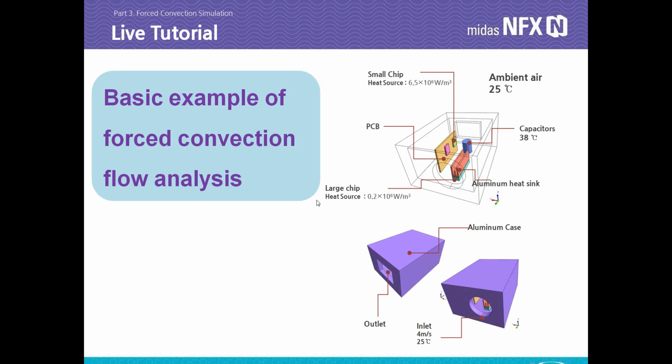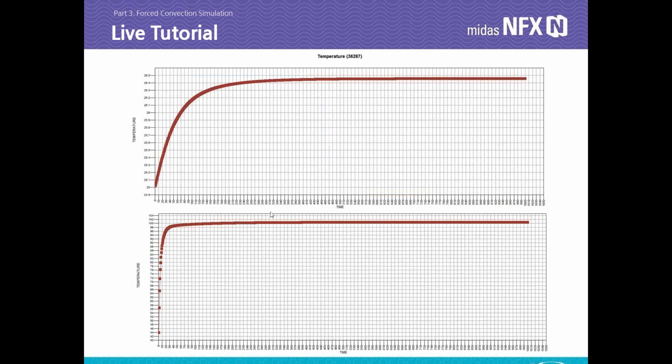Okay, let's go back to the presentation. This was because when you make the full simulation, the temperature is converging like that, so you see that you reach the steady state after around, let's say, 500 seconds, so you can say you have around the steady state here. So you don't need to make an analysis of thousands of increments, you can do 500.